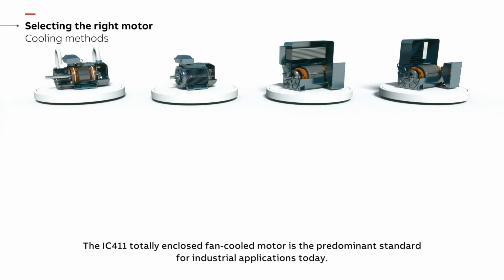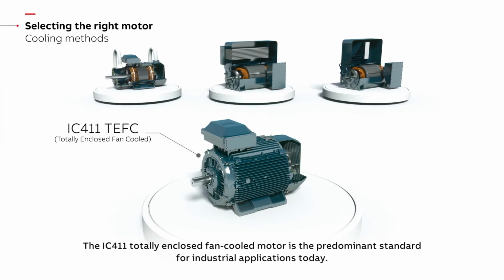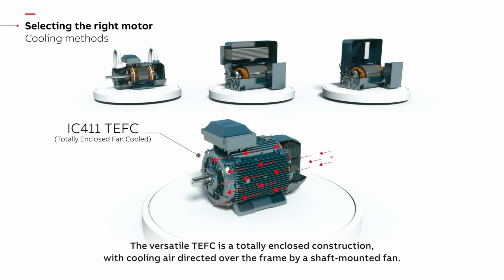The IC 411 totally enclosed fan-cooled motor is the predominant standard for industrial applications today. The versatile TEFC is a totally enclosed construction, with cooling air directed over the frame by a shaft-mounted fan.